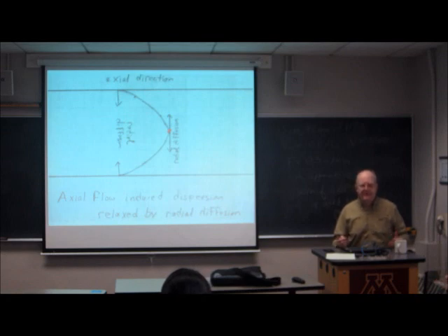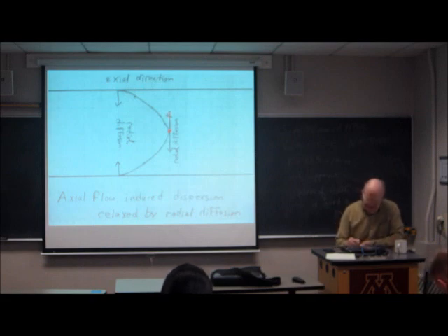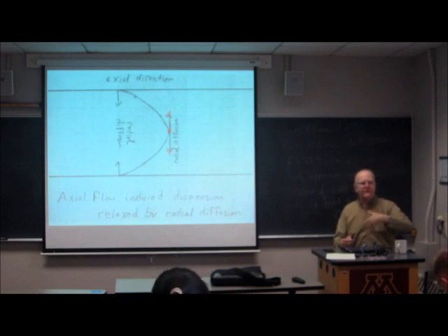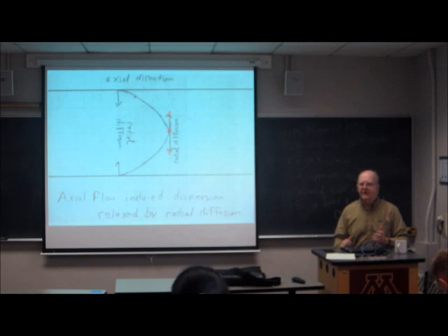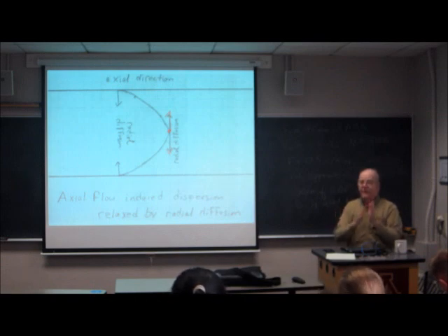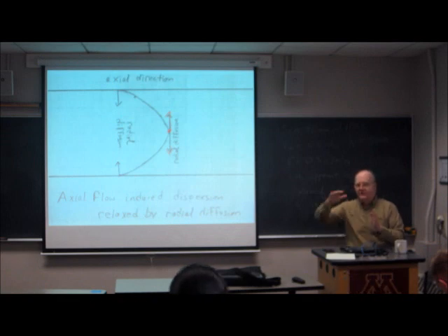They have to diffuse radially. Which way do they diffuse? Radially. These move that way and that way in random steps according to just simple molecular diffusion. But when they take a random step towards the wall, what's happening to their forward velocity? They're moving into a region of lower velocity. This is good. They're slowing down. We want them to slow down because they're in the front.